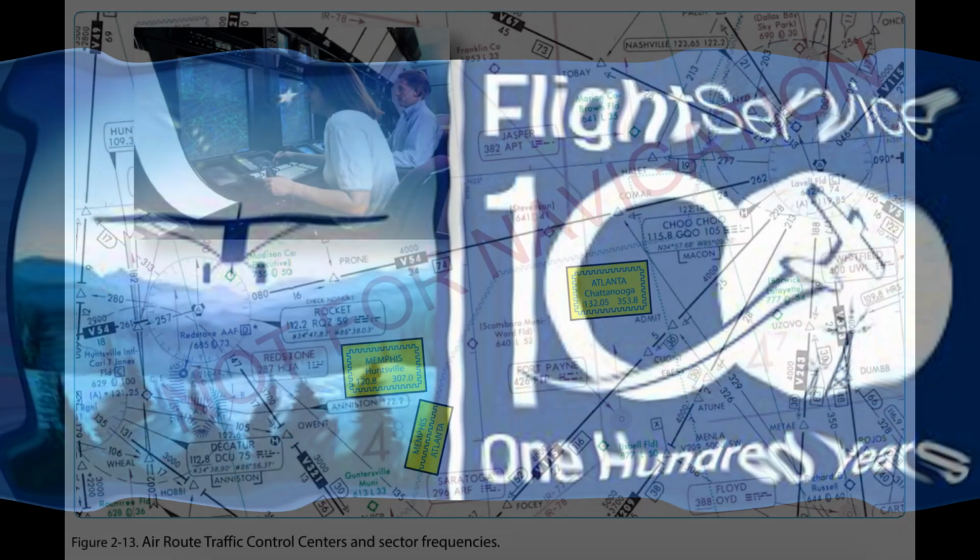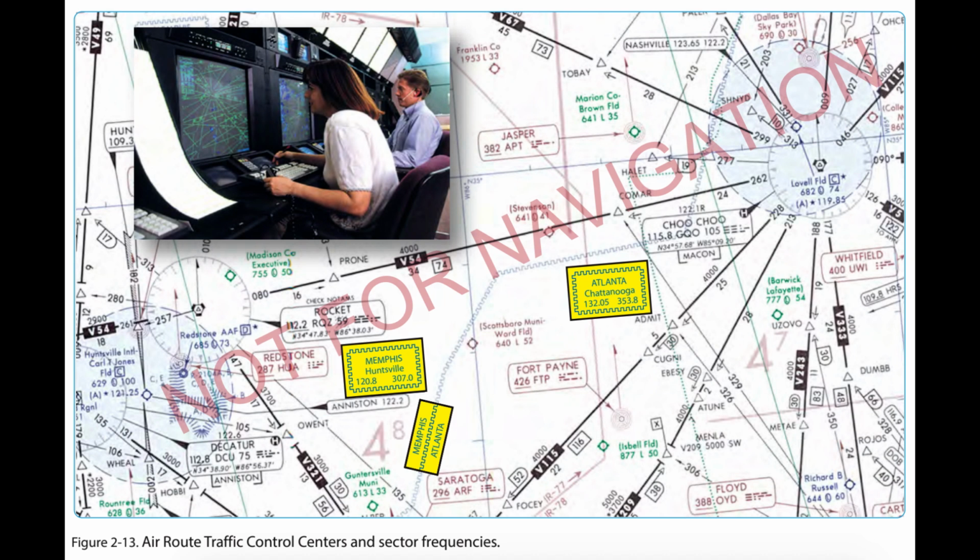In-flight requirements and instructions. The CFRs require the pilot in command under IFR in controlled airspace to continuously monitor an appropriate center or control frequency. When climbing after takeoff, an IFR flight is either in contact with a radar-equipped local departure control or, in some areas, an ARTCC facility. As a flight transitions to the en route phase, pilots typically expect a handoff from departure control to a center frequency if not already in contact with the center.